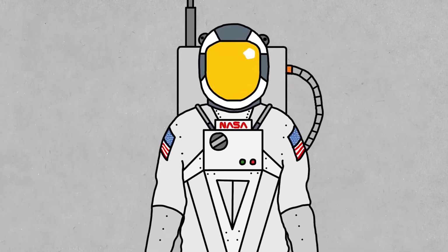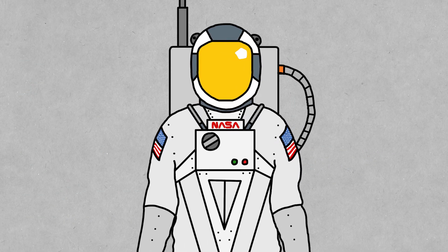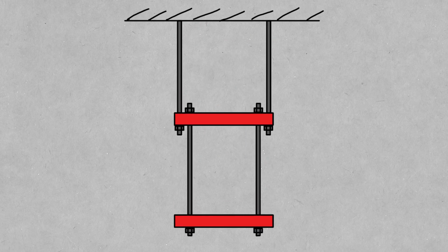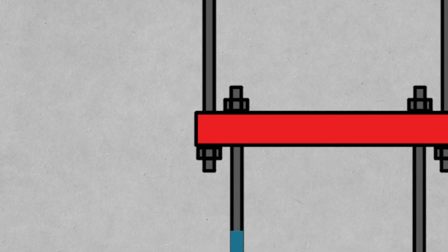So let's get into why the engineers were found at fault for the Hyatt collapse. When they reviewed the plan, they did not do an effective analysis of the design, and the existence of a massive design flaw suggests that they hardly considered it when signing off. This design flaw was an unavoidable side effect of using 2 rods instead of 1. When there are 2 rods, all of the weight from the bottom floor is placed on the beam for the upper floor. This force is then transferred through the beam to the single nut that is holding that beam up.